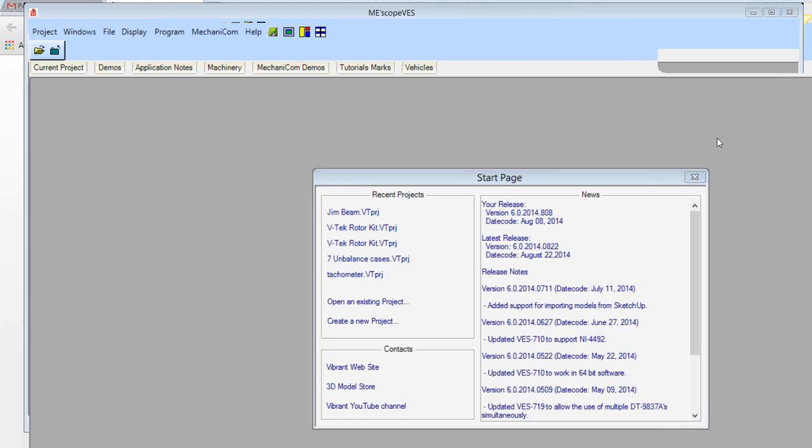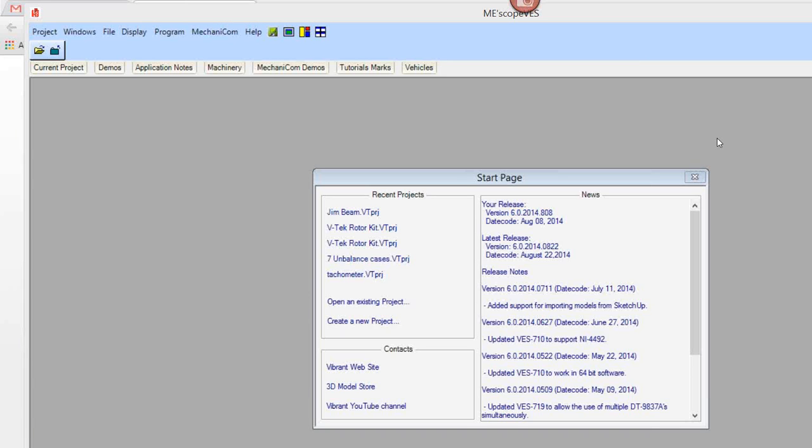Now, there's one more step involved here, and that is that we use an FRF-based curve fitting algorithm. All of our curve fitters presume or assume that our measurements have the form of an FRF. Now, in the case of an OMA situation, we don't have FRFs. We have cross spectra or we have ODS FRFs. So the first step we have to go through is to process that set of measurements with a special windowing.